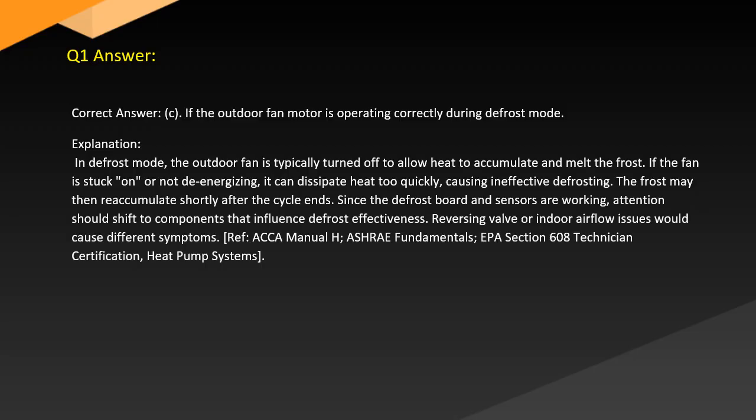Since the defrost board and sensors are working, attention should shift to components that influence defrost effectiveness. Reversing valve or indoor airflow issues would cause different symptoms. Ref: CAM Manual H. ASHRAE Fundamentals, EPA Section 608 Technician Certification, Heat Pump Systems.